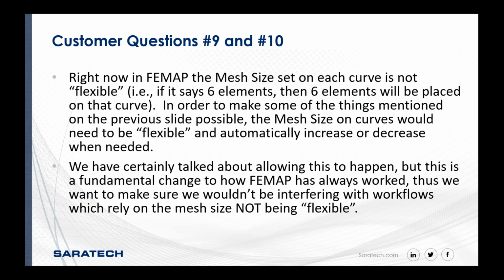Right now in FEMAP, the mesh size set on each curve is not flexible. If it says it's going to put 6 elements along that curve, then 6 elements will be placed on that curve. In order to make some of the things mentioned on the previous slide possible, the mesh size on curves would need to be flexible and automatically increase or decrease when needed.